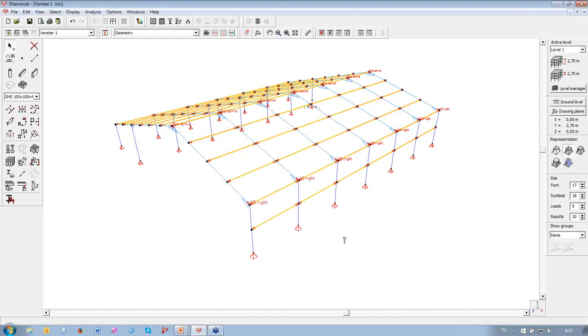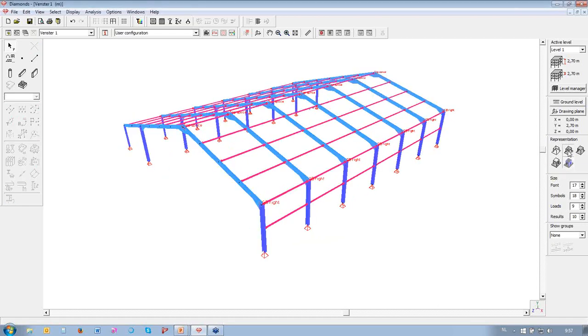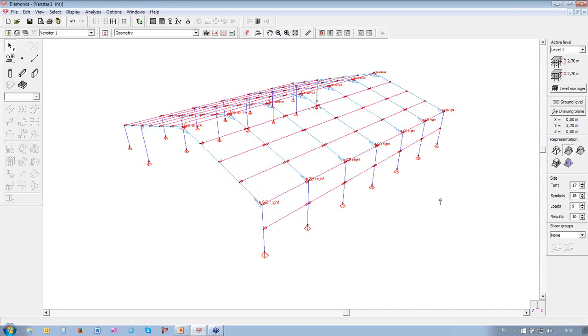Okay. So you can see they are now in pink. In 3D solid mode, it's much clearer that there are different types of elements in the structure, and with the control button, if you click once on one element of a certain type, you can select all elements.